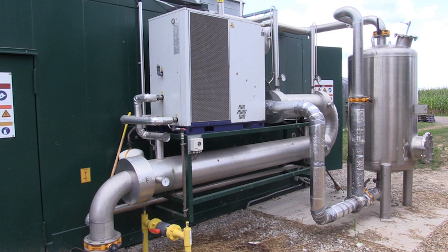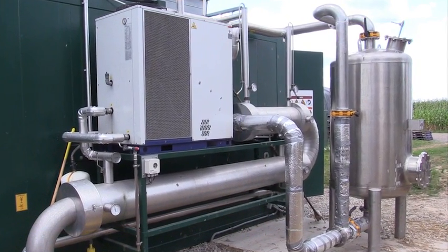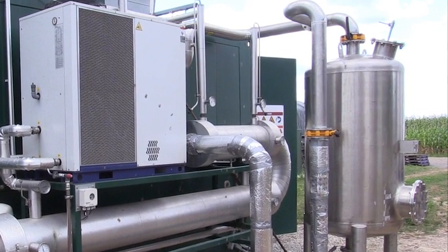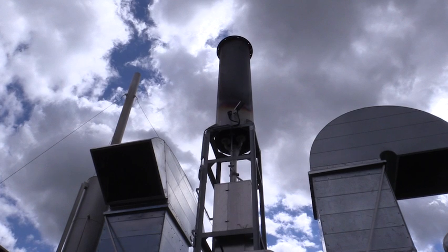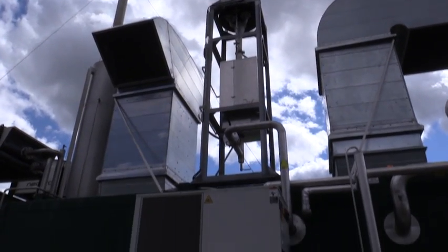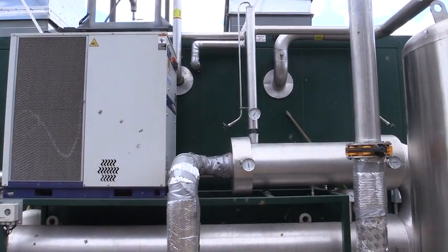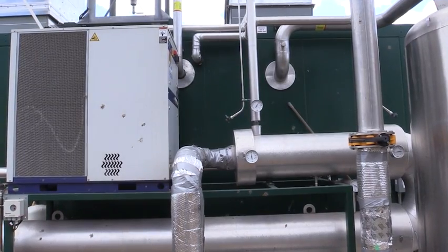Typically, the methane content of biogas ranges from 50 to 70% depending on the biomass input, commonly called feedstock, and the digester operating conditions. Hydrogen sulfide is a common trace gas of concern for manure digesters due to its corrosive and toxic properties. Biogas is used directly as a fuel source for the generation of heat, hot water, steam, or electricity. If refined and compressed, biogas can be used as renewable, compressed, or liquid natural gas.